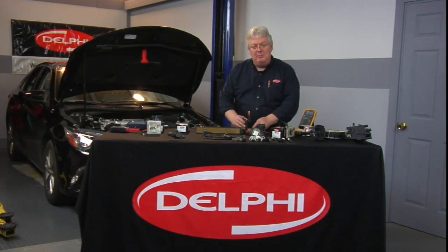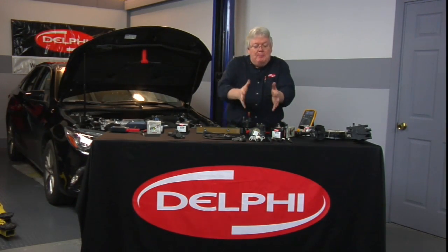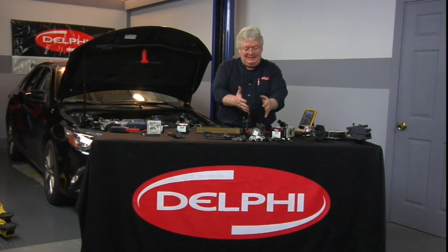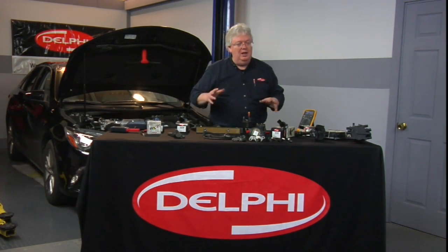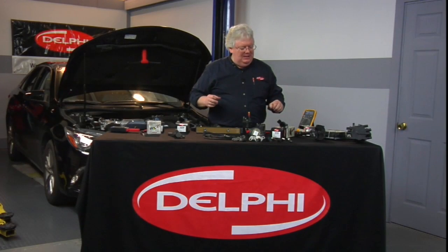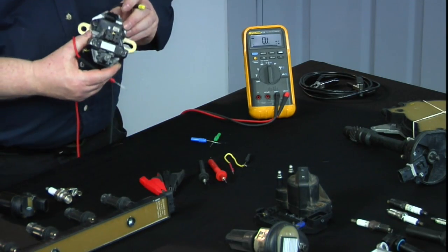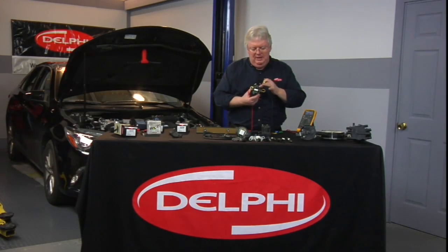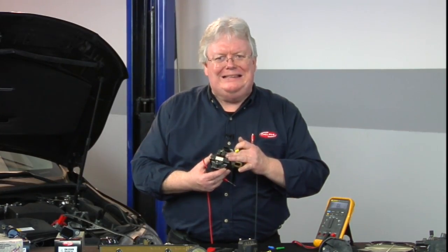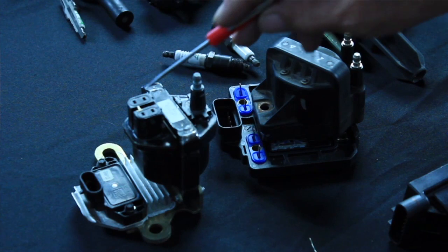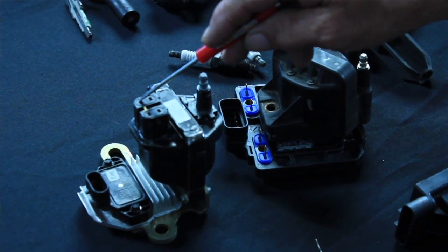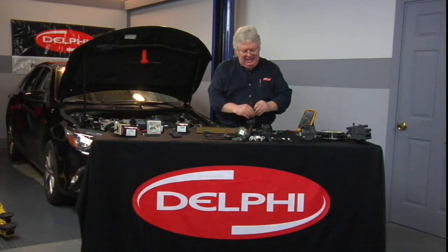We can do the same thing with a little bit more modern ignition coil and then bring it forward to DIS, and then finally today's topic, Coil-On-Plug, so you can see the transition of what you can and can't do. Here is an old coil from like this GM system, would be the distributed systems, single coil. We're going to go between the two primary windings, the power and the ground that's supplied by the ignition module, right here, my finger's tapping.